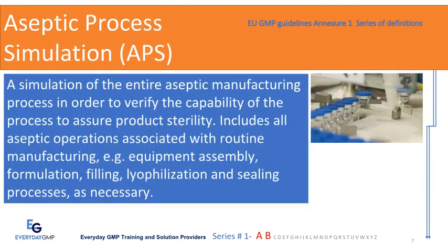Aseptic process simulation, APS, or media fill run: a simulation of the entire aseptic manufacturing process in order to verify the capability of the process to assure product sterility. Includes all aseptic operations associated with routine manufacturing, e.g. equipment assembly, formulation, filling, lyophilization and sealing processes, as necessary.